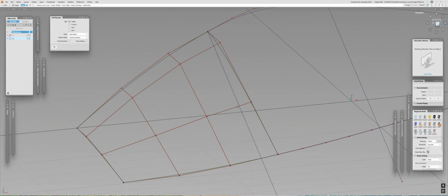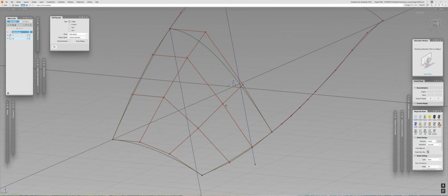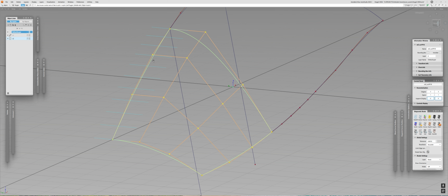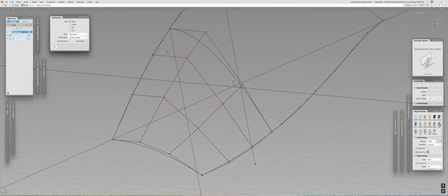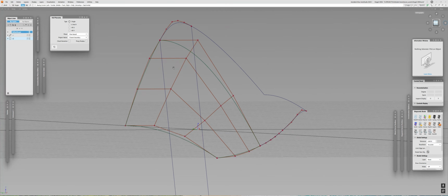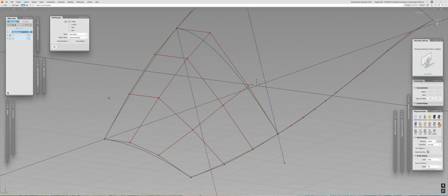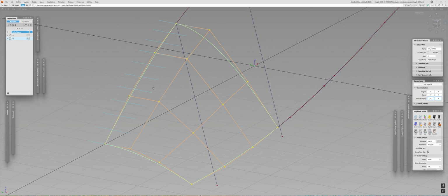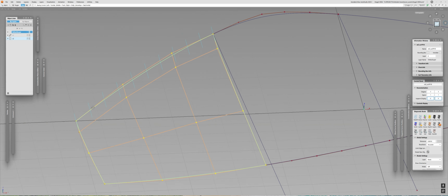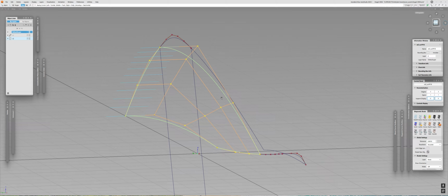Okay, and as you can see, even though I used a different tool, we are still under the history and there is no issues. If that was a rail tool and it was aligned tangentially to this surface, and I used the planarize hole command, it would destroy my history, and the continuity across the central line would not be guaranteed. But as we have the different tool, the symmetry plane align, in effect, it just makes our life so much easier.